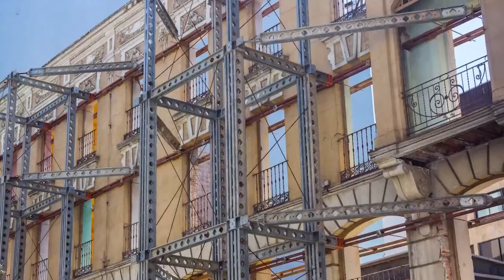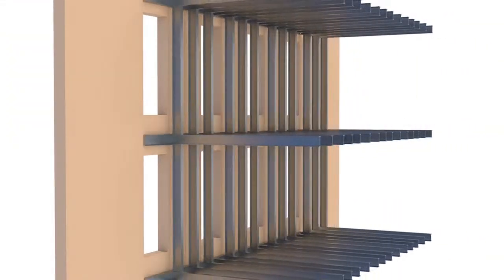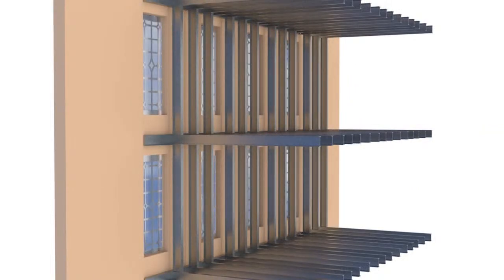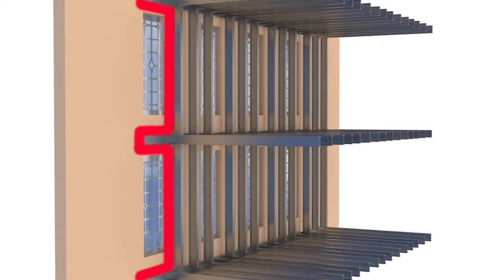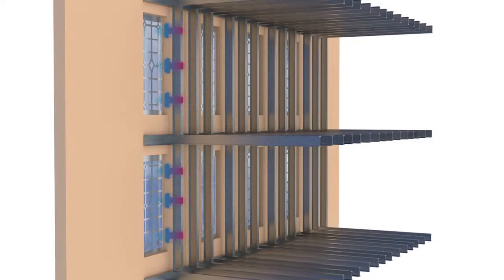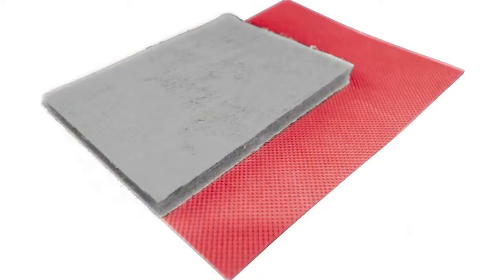Raptherm. At the more extensive end of building refurbishment are facade retention projects, where the majority of the building is demolished and replaced with a modern new build structure, retaining only the facade from the existing structure. While this method resolves a great number of the issues inherent in such projects, by simply replacing the problematic elements and features with modern equivalents, designing an effective interface between what is replaced and what is retained can still be challenging. Air leakage and cold bridging are the most significant problems to be overcome in these areas, so by combining a vapour-permeable, self-adhering air barrier membrane with a layer of high-performance insulation, Raptherm offers a simple and compelling solution to these issues.